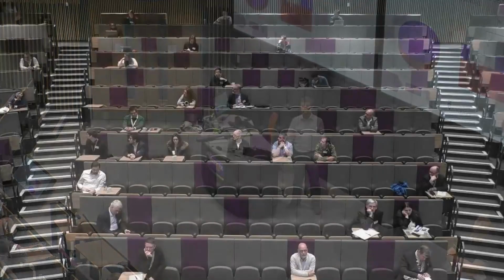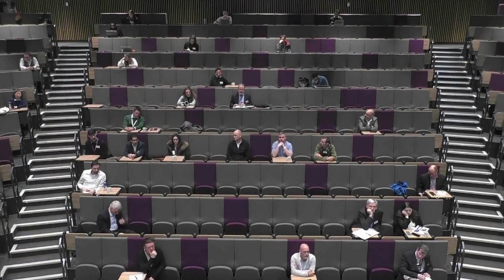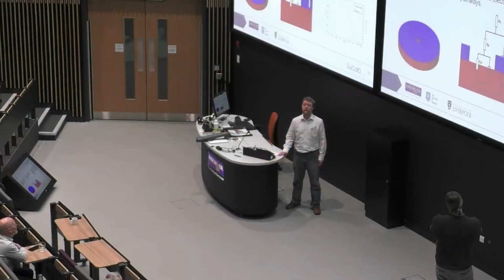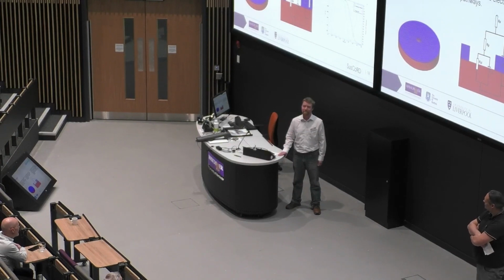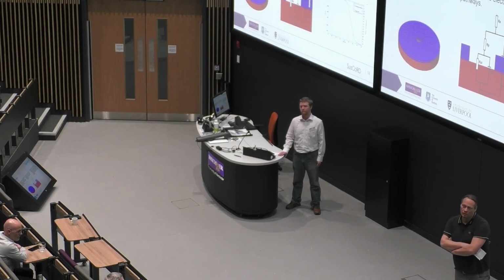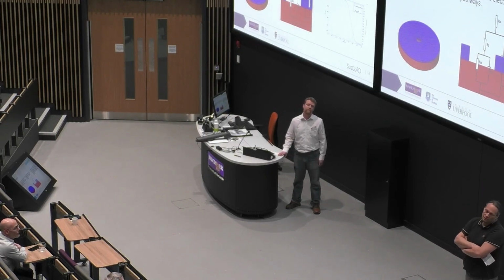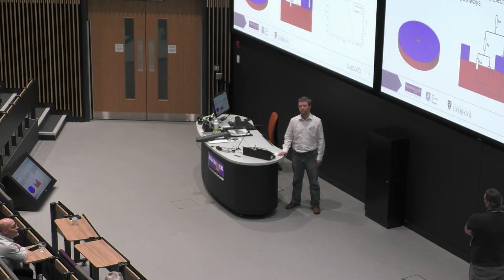How thick is it going to be on your coating? Say that again, sorry? How thick? For this data set just generated, it is 100 microns, but that can be freely changed. Yeah, I found that when it exceeds 300 microns, the impedance is not quite well on this thickness. We can't even distinguish corroded sample and not corroded sample. Are you going to change the thickness on your validation? It could be something to look into, but it is not the focus moving forward.